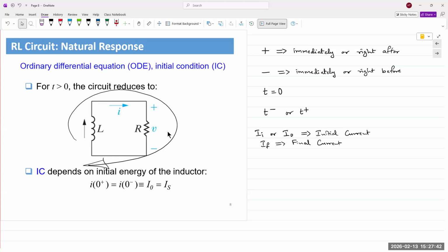It doesn't matter if that discharge gets interrupted halfway through. Let's say a capacitor is charged to 10 volts. It starts discharging from 10, 9, 8, 7, 6, 5, 4, and it's interrupted. It starts charging again. It doesn't matter. If you're writing the mathematical expression for that first portion of discharge, the initial value is 10 volts, the final value is 0.